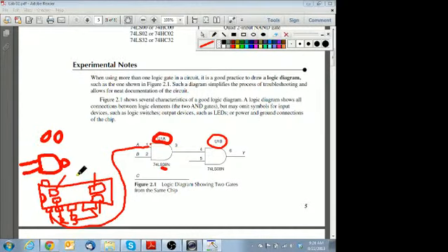And also on the board there's going to be a designator physically on the board. It's called silk screen. It's going to be white, printed on the board, so that you're going to be able to see the package and the reference designator, and this tells you the pin number. So you have everything you need to know for a technician to wire up that part and get the electrical connections proper. Okay? And if he has any questions, of course, you can always consult the data sheet.